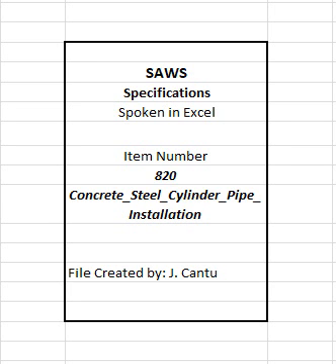22. Gaskets: randomly test rubber cord for diameter, tensile strength, elongation, compression set, hardness, and specific gravity after oven aging on 1 out of 100 gaskets.